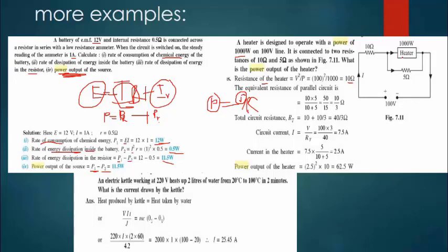So similarly, we have to find how much power the heater is losing, so that we can know how much it can give as output. Okay, yeah. So to know the amount of power lost as heat, we first have to know the current that is passing through the heater, and it is not simply the 100 volts divided by the resistance. No, these are operating values, so you should not use them to calculate current.